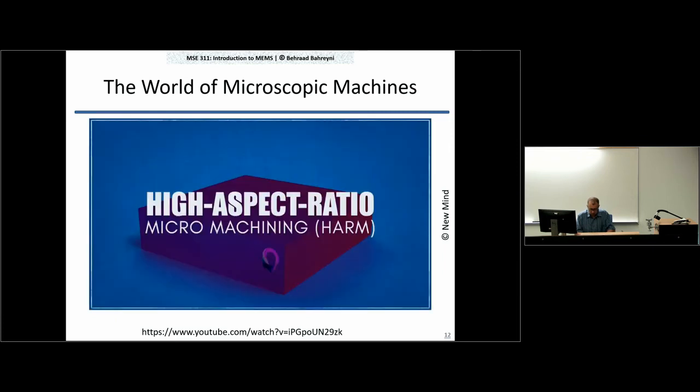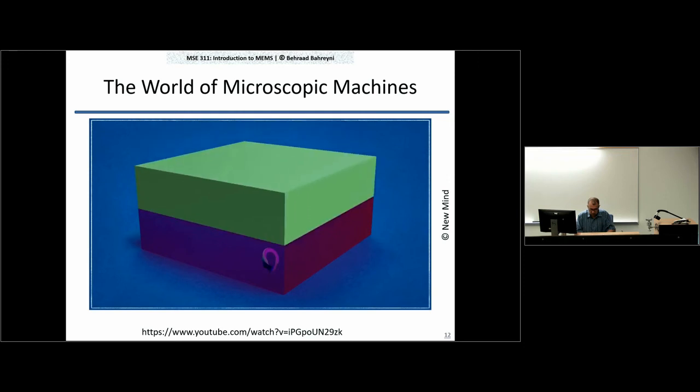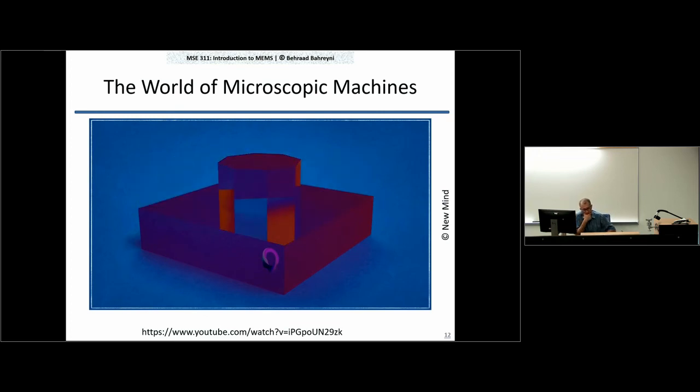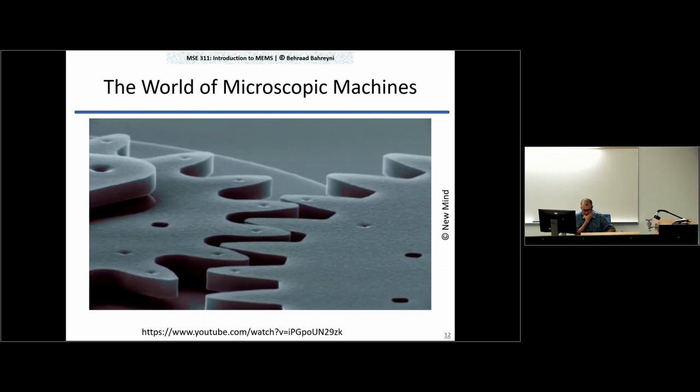High-aspect micromachining differs dramatically from the other two techniques in that it's reminiscent of traditional casting. Typically, a metal base is first coated with a thick acrylic layer. Then, through a mask, X-rays are projected onto the surface, creating a shaped cavity. Electroplating is then done to fill the cavity with metal, and finally the acrylic is etched away, leaving an embossed metal structure.